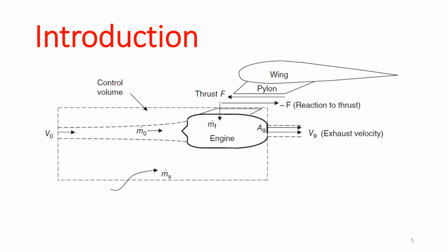But what we can do is use this flow stream that is affected by the presence of the jet, though that has a variable area as well. So it is complicated. We will talk about it later in this chapter, and today if we have enough time. But the point is you want to choose your control volume to make your problem as simple as possible.